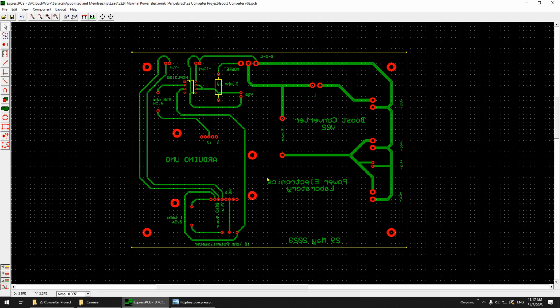This design is only single-sided, and this one is for DIP. DIP means that you have to drill a hole in the PCB. There are DIP or SMD. SMD you can do that also, but for FKE, UTM, we don't have the facility to do that. You need to have a different facility to do the SMD design. SMD means surface mounted device. DIP, you need to drill a hole. So that is the first thing that you need to consider: setting up the size and making sure it is much smaller than the PCB you use.